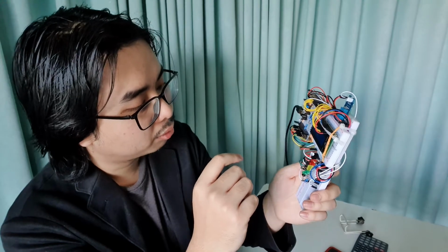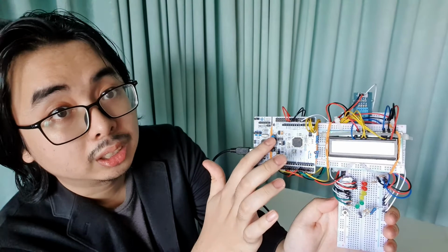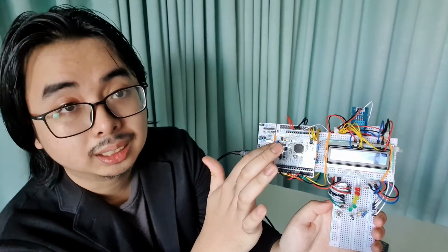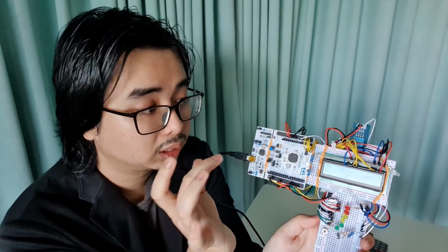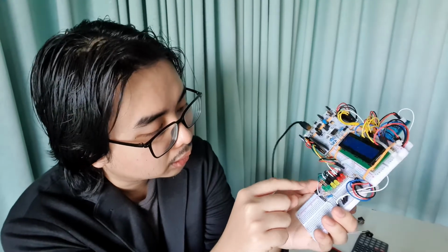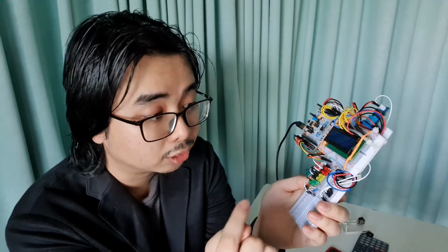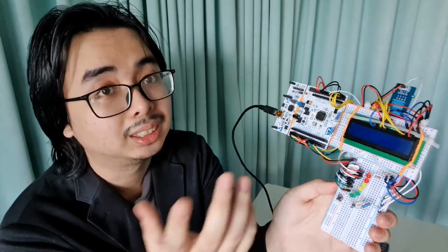Now, if you look carefully, you can see there is a switch here. There are two switches, one that is connected to the processor and one that is external. The button on the processor, as I mentioned earlier, is the negative switch, meaning it inputs a 0. For the external switch, we made it a positive. So we designed it with 3.3 volts connected to the switch, connected to a 10 kilo ohm resistor, then connected to the ground. And PB8 is connected between the resistor and the switch, as you can see from the circuit.